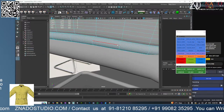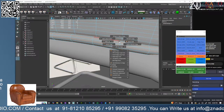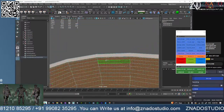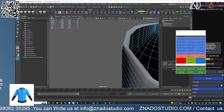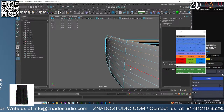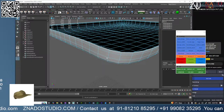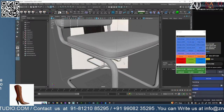For this as well, what I can do is select this, set alternate edge, delete, select, select alternate edge, delete. Done. This also I'll select. The internal edges which are not required, I'll just select and delete. This is not required. This is not required. Delete. This is also not required.